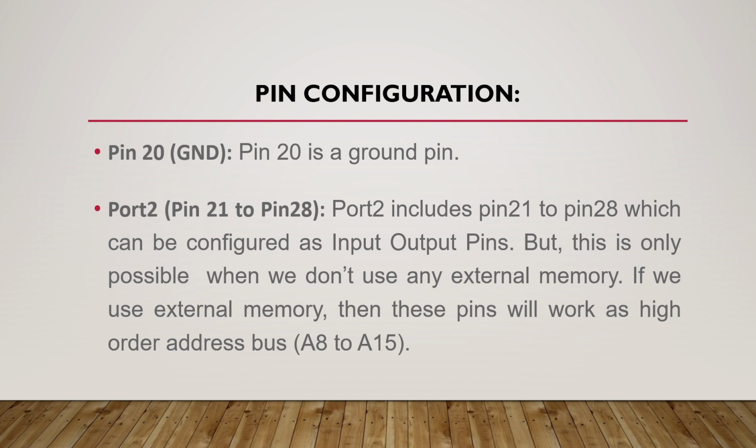For that, we connect external memory and use it with your 8051 microcontroller. When we add the external memory, your port 2 will act as an address bus to that external memory.